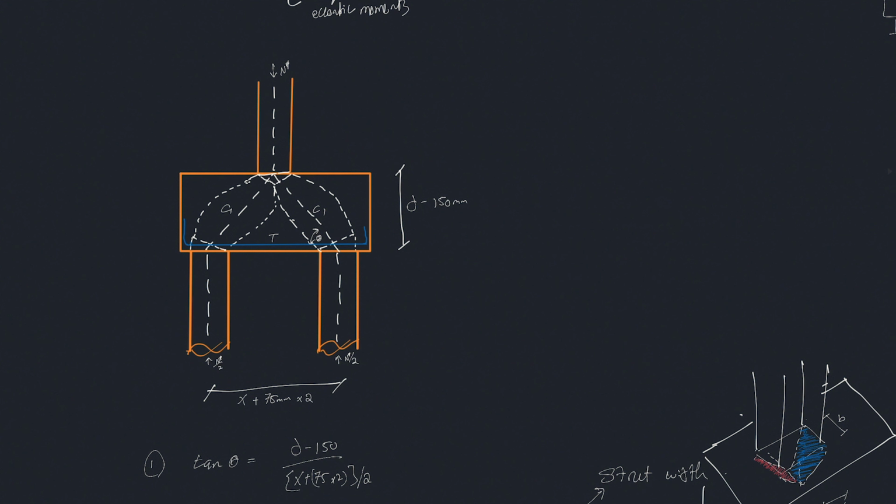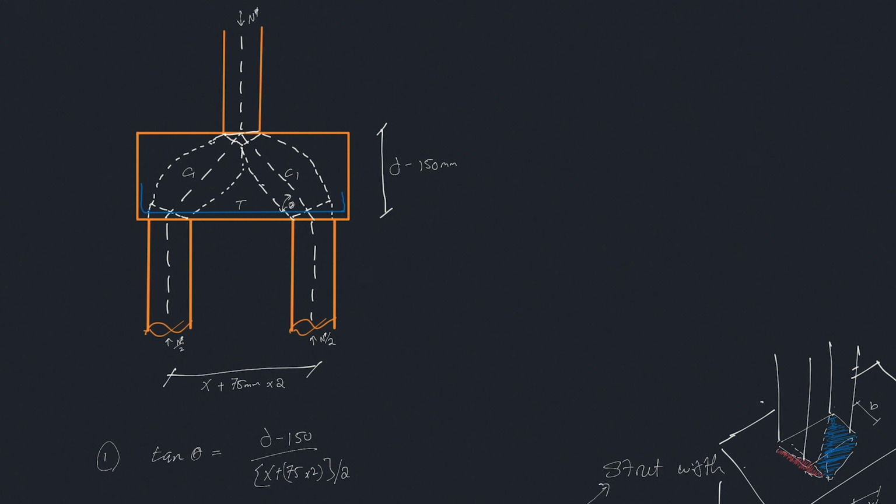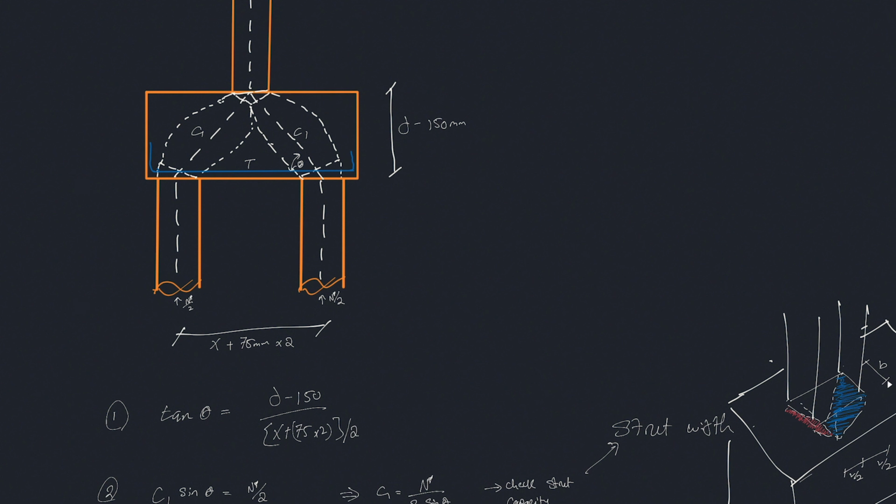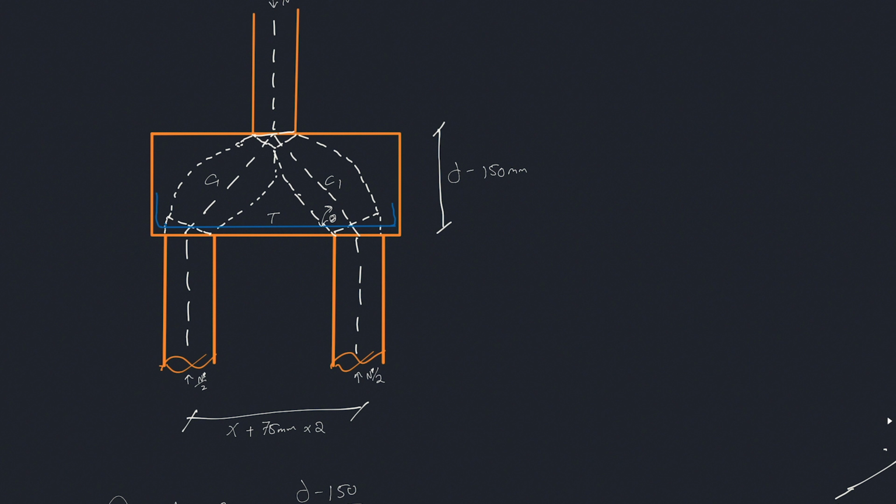Now let's jump into a two pile cap, where it can start to get a little bit more interesting and complex. So with a two pile cap, what we have here is a slightly bigger, again, strut and tie model. So we have our compressions going from the column into the piles, and we have our tie members at the bottom. This distance here is exactly similar to how we worked it out previously. So you can conservatively assume this is about 100 mil because of your cover.